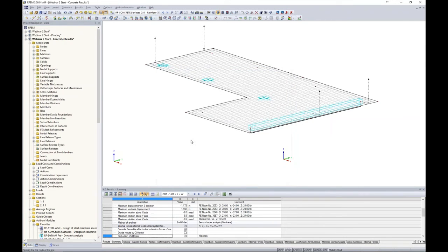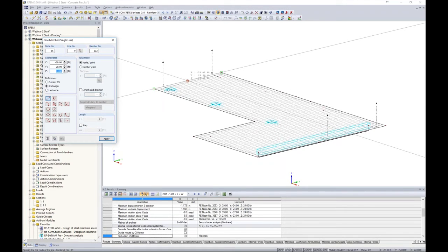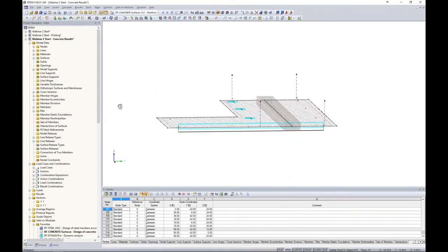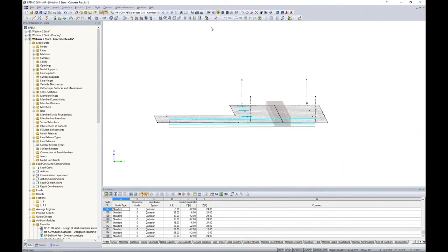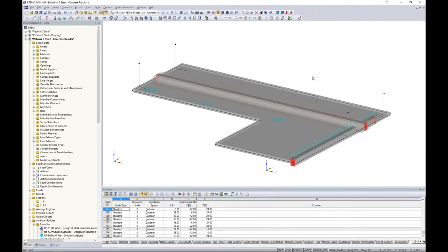So when I click OK, I can begin by modeling my new member. I will snap to the middle point of this line over here to make my result beam section right down the middle of this slab. You can see the program automatically snaps to the perpendicular section, just like what we'd see in AutoCAD. And here is my result beam. So we can see that 4-foot wide section. We can even render this if we'd like a little bit clearer view on what's exactly going on.